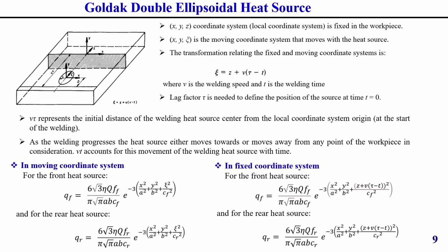In the front part equation, directly I am just showing these things. Okay. So, the front part of this equation for moving coordinate system will have a factor ff. How this factor comes, I have already told you: ff is 2 into cf divided by cf plus cr, and fr is equal to 2 into cr divided by cr plus cf, this you should keep it in mind.